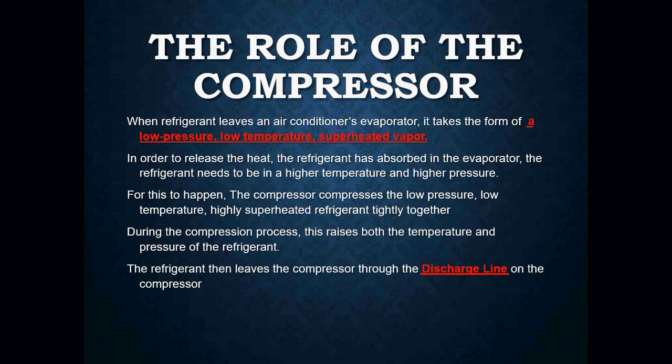We need to keep in our heads that the compressor only compresses. It moves the refrigerant through compression. In order to release the heat that the evaporator has absorbed, that refrigerant needs to be at a higher temperature and a higher pressure.